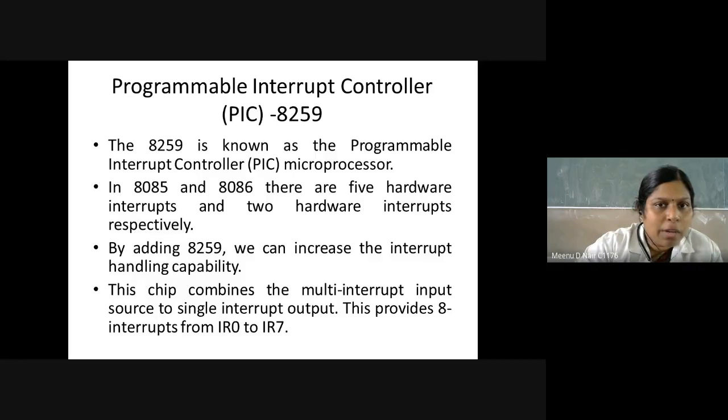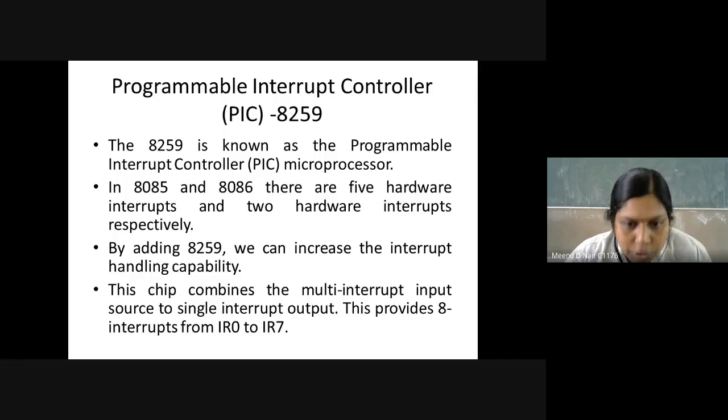So what is the requirement of this programmable interrupt controller? Usually in 8085 and 8086, you have very few hardware interrupts, I'm not speaking about the software interrupts. In 8085, you have 5 hardware interrupts, and in 8086 only 2 hardware interrupts are available.